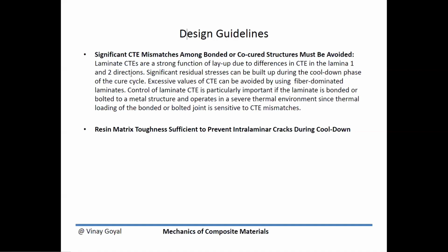Excessive values of CTE can be avoided by using fiber-dominated laminates. So you can control the CTE behavior, and you can even tailor it to get it closer to the metal if that's what you're bonding it to. If you're bonding metal to composite, reducing the CTE mismatch can be useful for the bonded joint design.